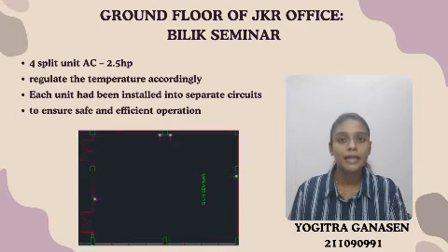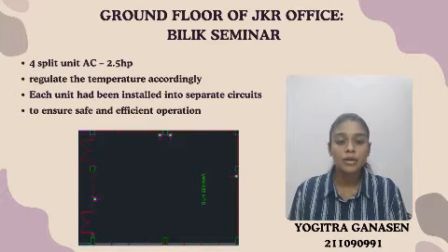The bilik seminar had been installed with 4 split unit AC. Each of the units is 2.5 horsepower. This is to regulate the temperature accordingly. Each unit had been installed into separate circuits. This is because connecting more than one unit to a circuit will overload the circuit. Hence, this is to ensure safe and efficient operation.